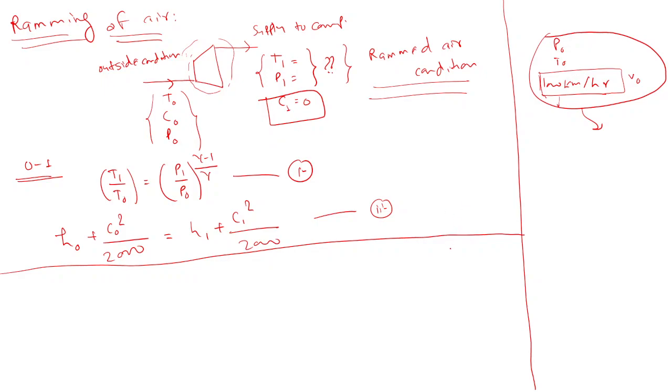Sir, here enthalpy is a function of internal energy and the flow. Enthalpy is a function of internal energy and flow work. Enthalpy we have defined as U plus PV, and U is the internal energy and PV is flow work. So for an air open system, anywhere we always use the enthalpy only.